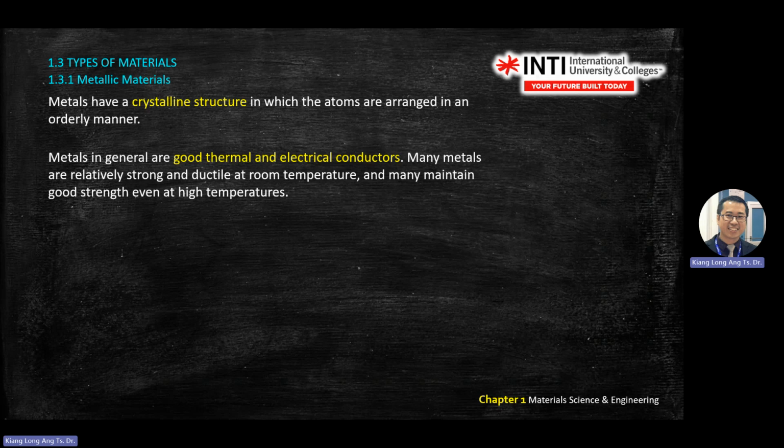All right. So this only appeared in metallic material, and you learn in chemistry an element called polymer. This one also has the same principle. However, the way they arrange is a bit different. The way metal arranges itself and the way polymer arranges is a bit different. So in chemistry, you learn about bonding, right? Chemical bonding, covalent bonding, secondary bond, single bond, and all this. Okay, so the first technical word for today is crystalline structure. What is crystalline structure? It means the atoms are arranged in an orderly or repeated manner.